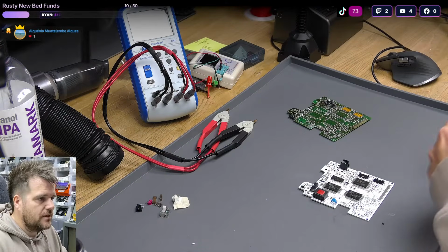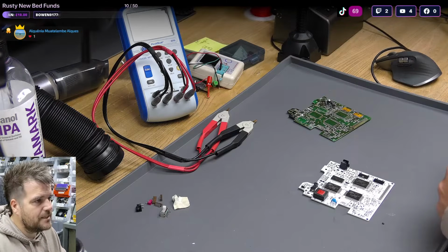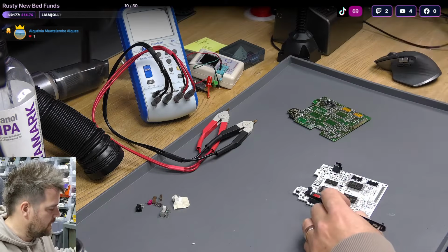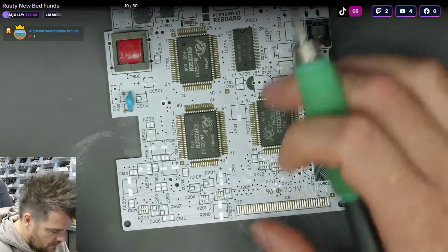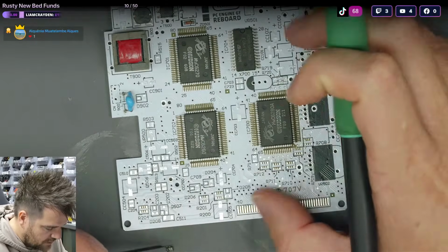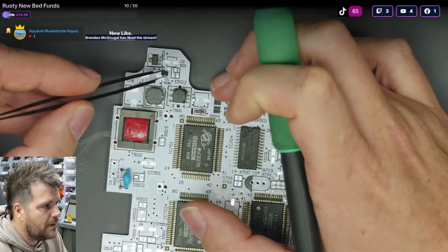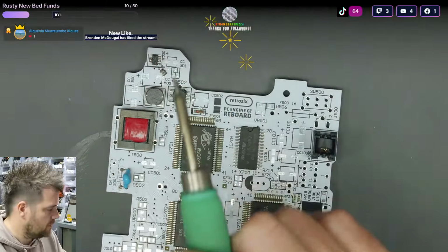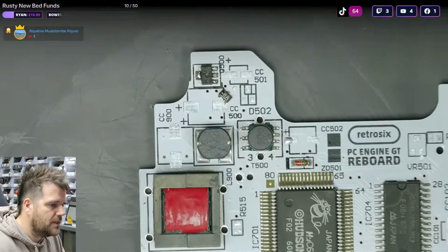It's not that specific about testing the item. It's about identifying the item. So you don't really need high quality internals. So buying a cheap component tester is probably as good as an expensive one for the most part. Whereas buying a cheap LCR meter is nothing like buying a good one. So it's just about knowing where I want to spend my money and not waste it, basically.